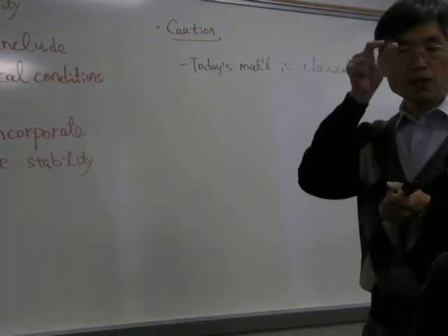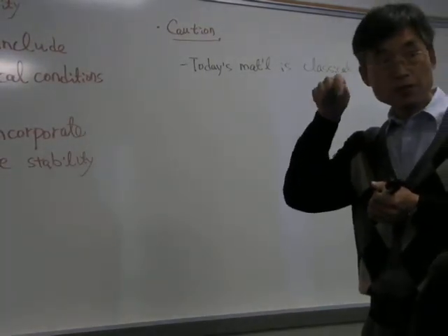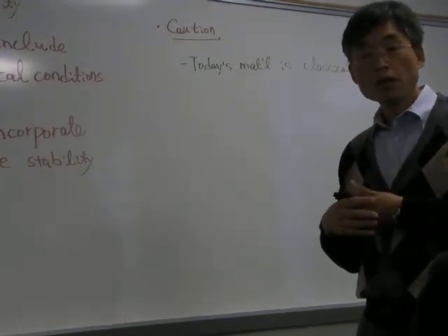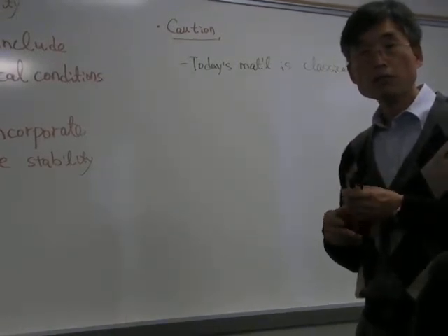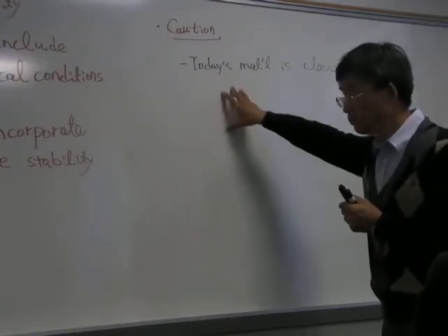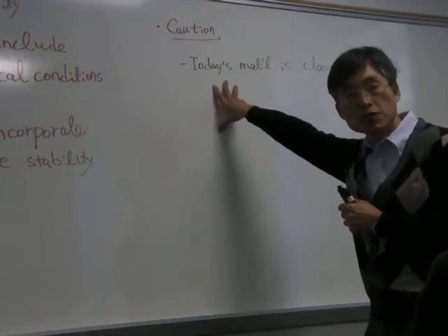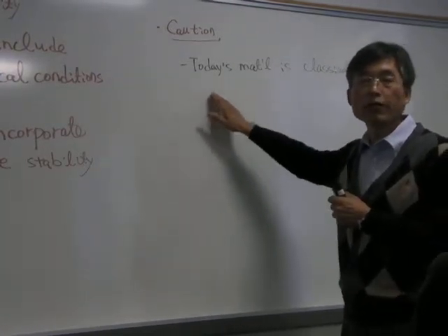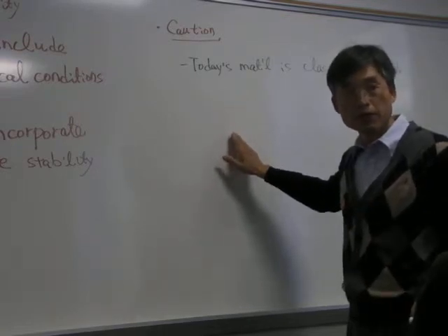Typically we use the ordinary method of slices. It requires long calculation time, and we usually use the dedicated software. Same thing for the dynamic slope stability problems. I will talk about how we can incorporate it conceptually.